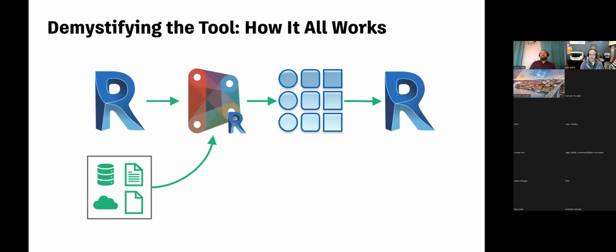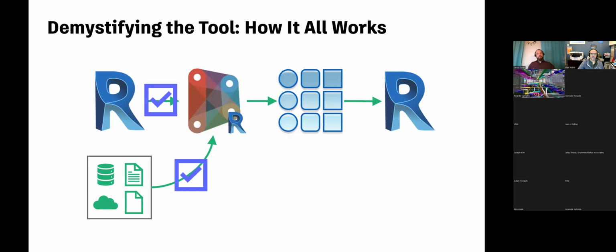So understanding how this process all works, we already know how to set up a number slider in Dynamo because we're Dynamo experts. And we already know how to move Revit data into Dynamo, like Select Model Element, Get Parameter Value by Name, and so on and so forth. What we don't know is how to move from Dynamo for Revit into generative design, or Dynamo really into generative design.